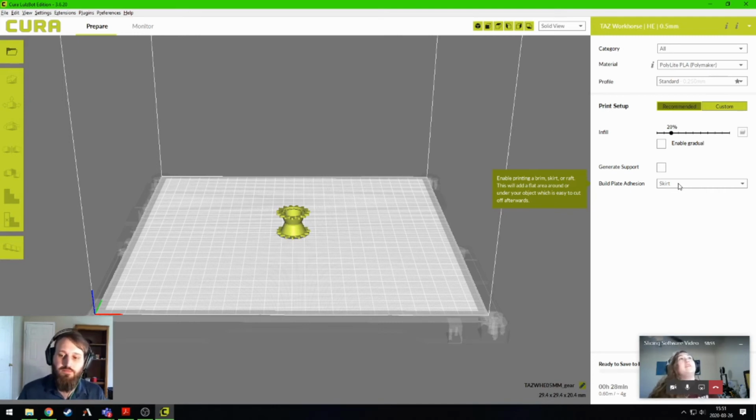So when I was having issues with it sticking with the normal bed that it came with, I would use painter's tape over top, and that would help for the time being. And then another tip that I learned from forums and things like that was to take regular stick glue and apply just a little bit. You don't need to dump it all on there. Just a small layer of it will typically do the trick too. Yes. There's also hairspray adhesive. So you could use.